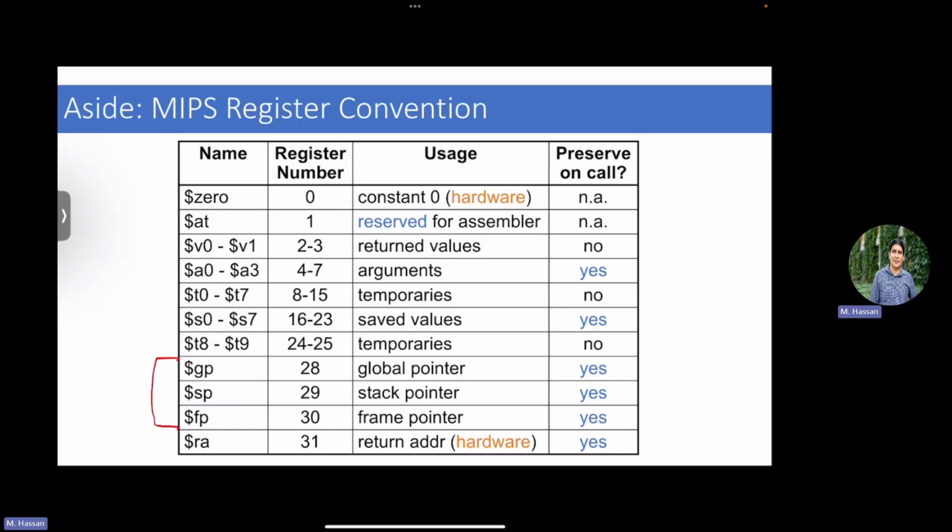Now, relating this to the hardware, we said the arithmetic instructions operate on registers. Registers are stored in a register file. In 3DQ, did you come across building register files? Like just a big chunk of memory that basically works as very fast memory to access, right? The idea is that in this MIPS machine or in even modern machines, those registers are tightly coupled to the processing pipeline. They are close to the ALU, which means this is the fastest memory you can access, right? You always prefer to access the register file than to go to the memory, because it's just a single cycle access time.